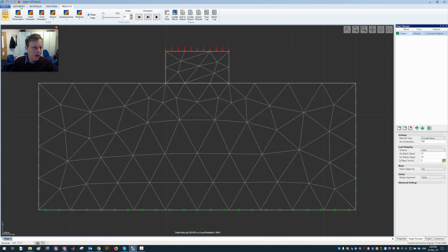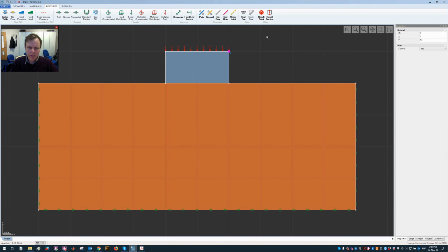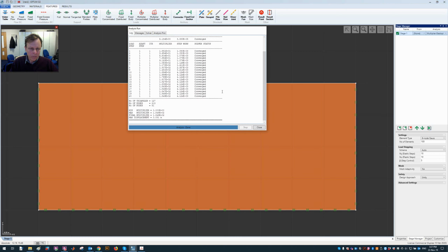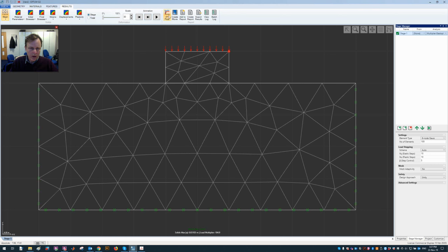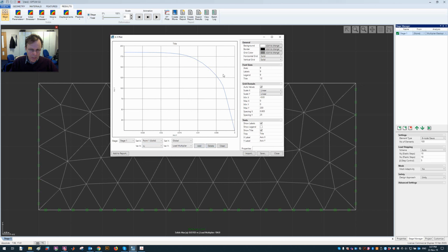That's not too surprising. Now, if you want the actual load displacement curve, you would insert a result point up here, and then let's do that and rerun. And we can then go into XY plots and then plot. Well, the UI is going to look a little bit awkward, but we could plot the numerical U, the total displacement. So that looks something like this.